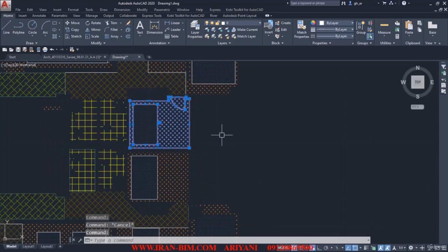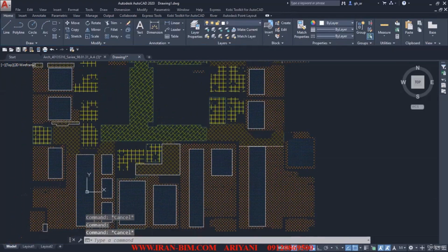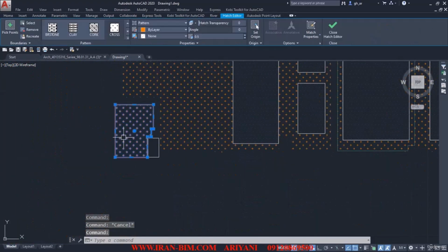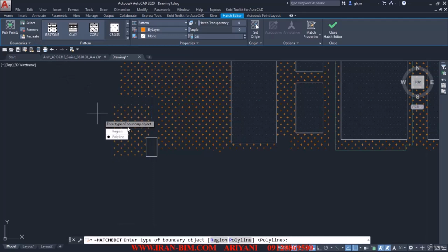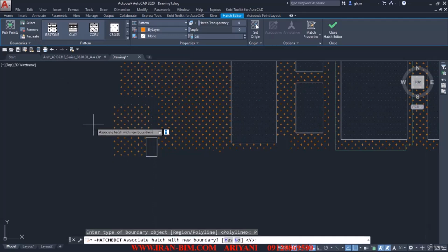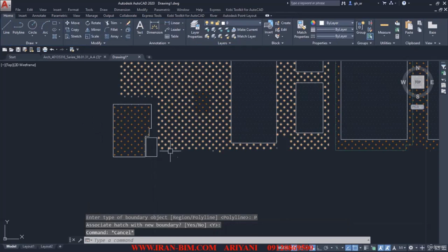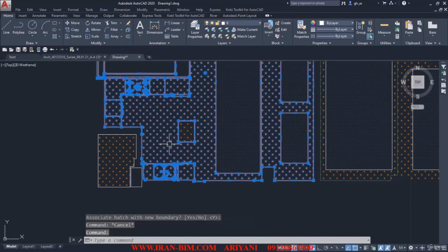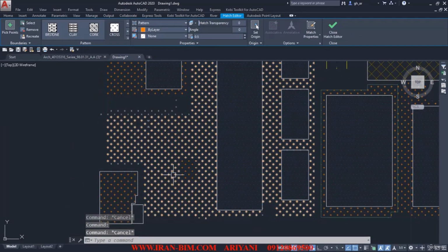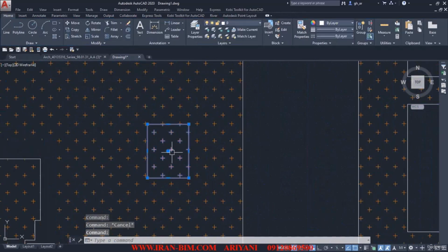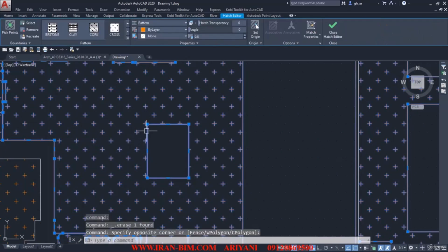And then for each of these spaces that you see here, if we select them, we have an option here. Let me just take a look at it. Right, it's right here. It's recreate and then polyline and then yes. So this just creates the outer line, which separates this layer from the other ones. And then this part over here hasn't been drawn out nicely enough. So I go here and then I'll delete this one. Let me just select this.